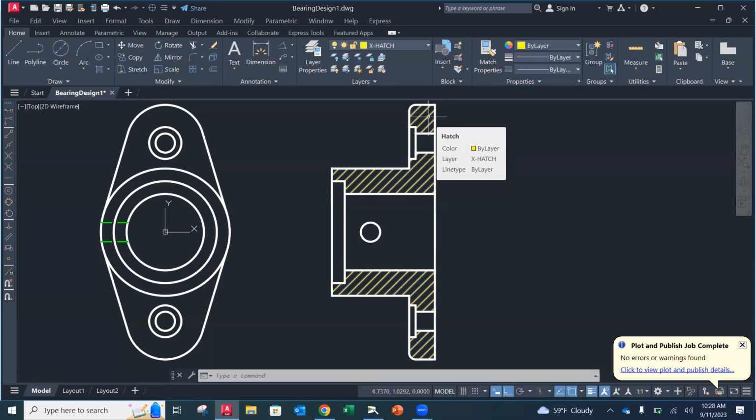Okay. So good geometry here, nice clean lines, using your object snaps, having single lines, no overlaps. It's really important. Here, the parts are a little bit more simple because we're learning. We're at the beginning of our sectioning journey, if you would. But as things get more complex, it gets even more critical. So if you did have any difficulties, or if it didn't recognize an area, go back and check to make sure that you've got good connections and good geometry.